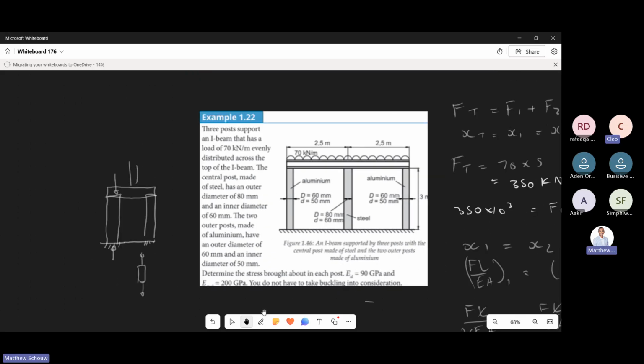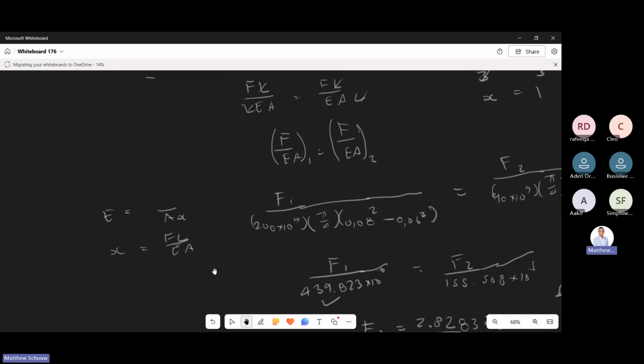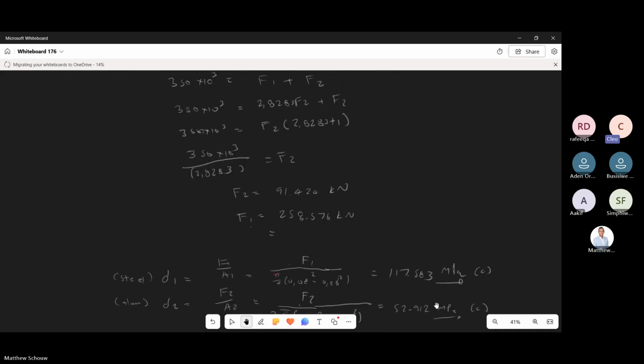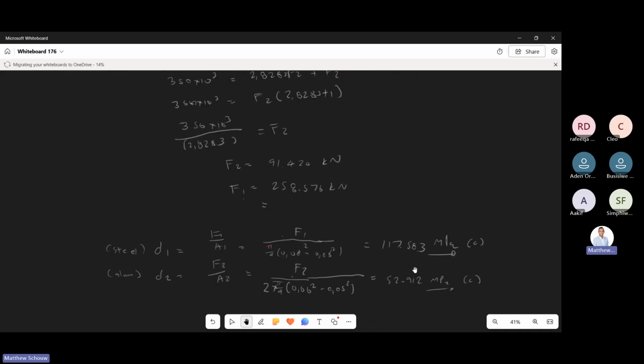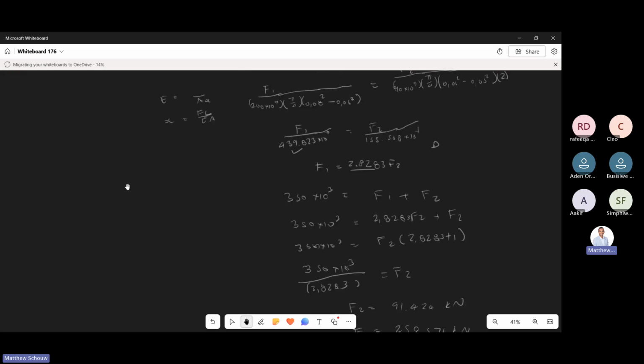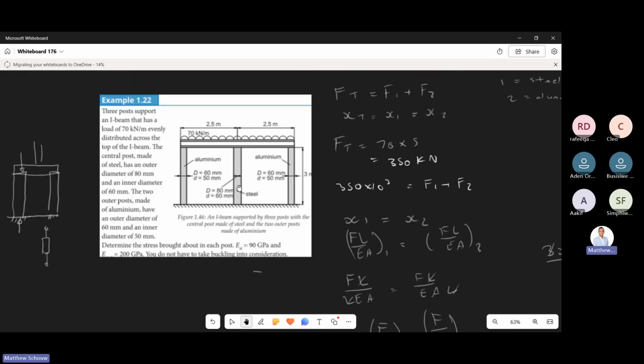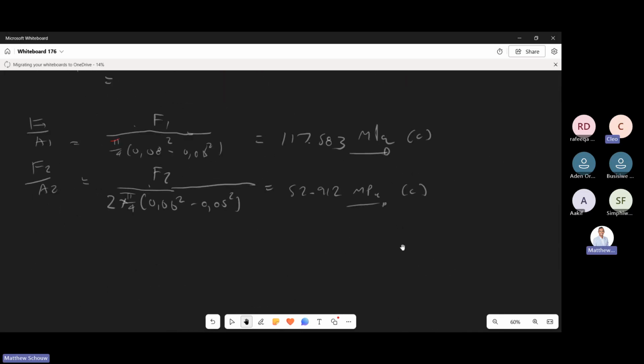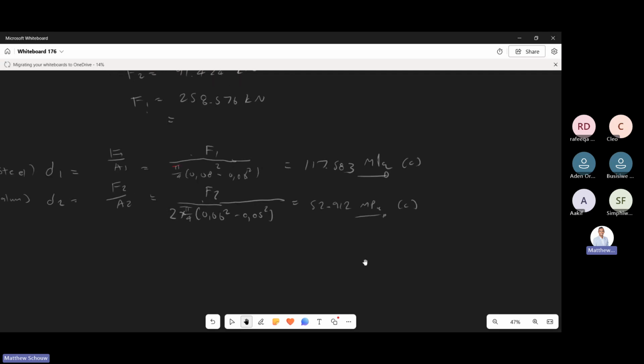Okay. So in terms of the values, what do you look at? Do you look at the stress or the extension? You're asking a good point. You want to look at the stress. So on a practical sense, these are the stresses induced due to that force. Now, if I look at the allowable stress, the yield stress, like when you buy material it comes with a standard stress, like that certificate.